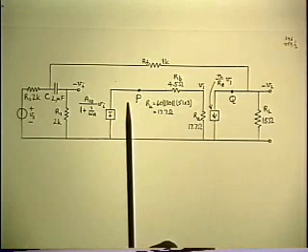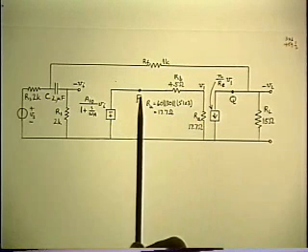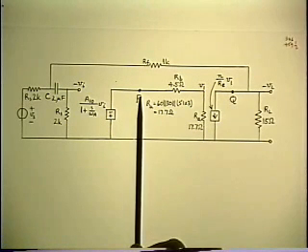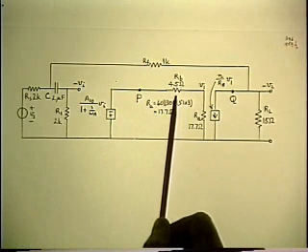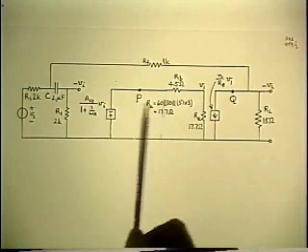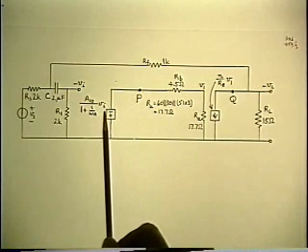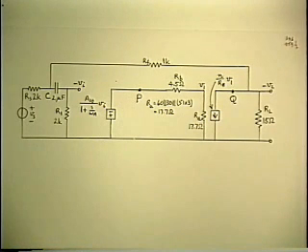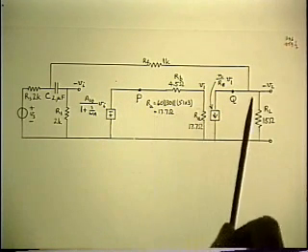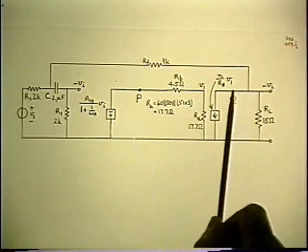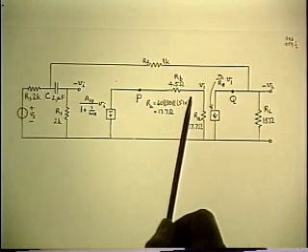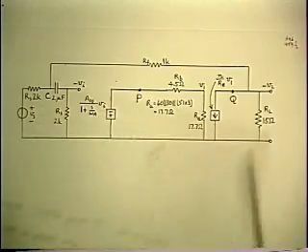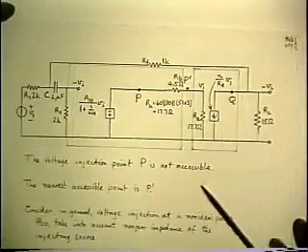But let's go back and look at what would happen if we did do voltage injection at point P. We could do it analytically, but we couldn't do it on the bench because point P doesn't exist physically. Because the RB, 4.5 ohms, actually represents the output impedance of that driver amplifier. So you can't get at this point. So if we were in a situation where point Q didn't exist either, and this is always going to happen in practice, we still have to come down and look at what happens if the ideal point is not accessible.